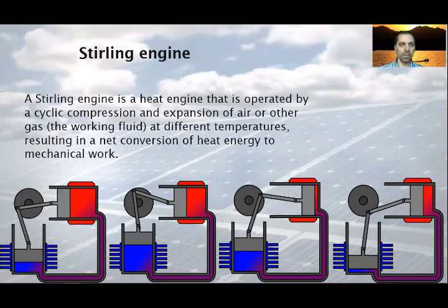Three. Almost all the gas is now in the cold cylinder and cooling continues. This continues to reduce the pressure of the gas and cause contraction. Because the hot cylinder is at a minimum volume and the cold cylinder is at its maximum volume, the volume of the system is further reduced by compression of the cold cylinder inwards.